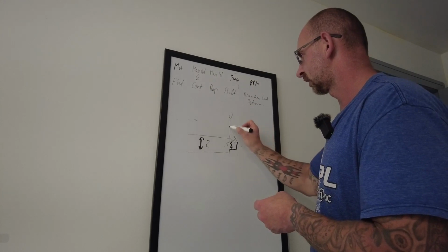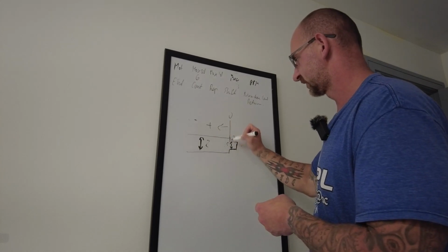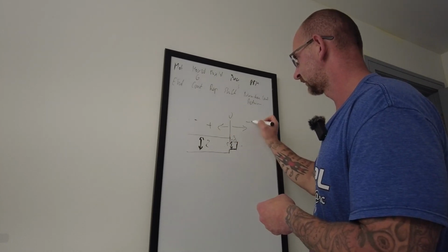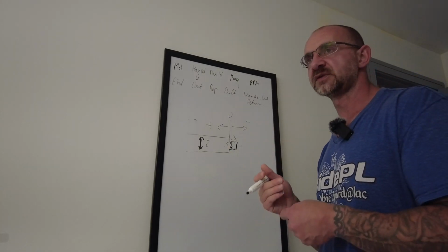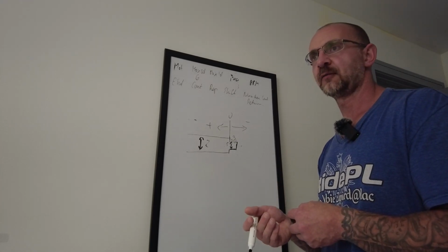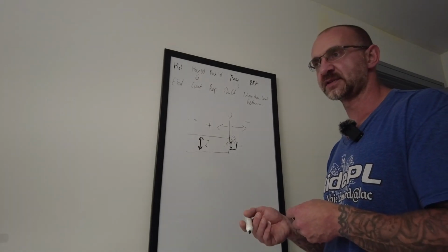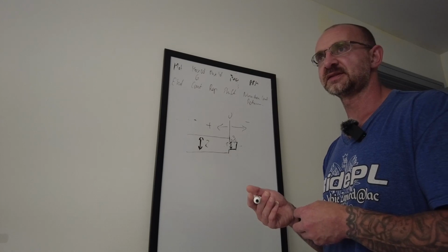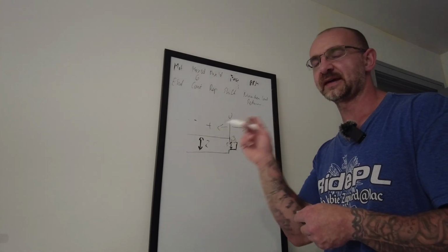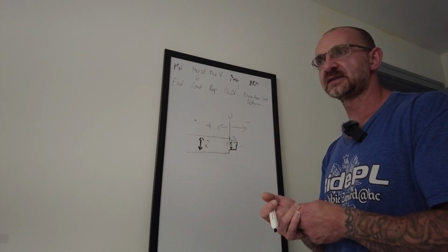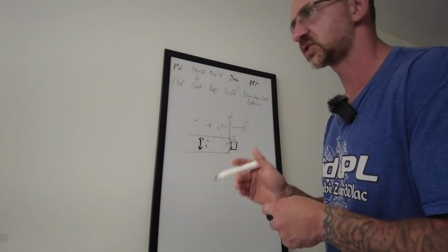the way we program, remember we program everything in the positive here. We program from a 0 that's set everything in negative here, okay? There's a sense because technically most of the program you're gonna go towards the left side. I think it was a really great idea on Mazak's part that we don't have to put minuses each time, especially if you have a lot of units, a lot of programs, a lot of lines. It's just not necessary, and I've had a problem where I had to program a Siemens control and I had to keep pressing minuses on everything. It saves you a lot of time, and like I said, I'm really happy that Mazak went that way.